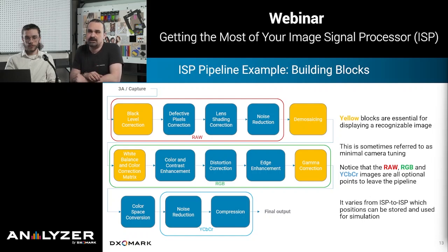And then typically, before you go to the final saving of the image, let's say, before you get to the JPEG encoding, for instance, there is another conversion of color space, which typically dissociates the luma channel that represents the lightness of the scene, so let's say the black and white correspondent of your image, your grayscale image, from a chromatic component on 2 different channels. There are several reasons to do this.